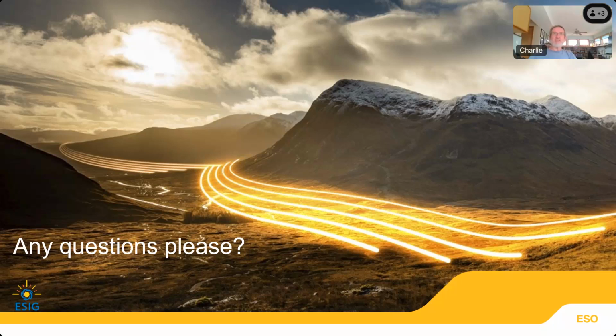Are there any regions within GB or other interconnected regions where inertia requirements are shared between regions? Is there a mechanism to coordinate this process? So GB is an island grid. It's a power system which is unique to GB. So whilst we're interconnected with HVDC links to Europe and to Ireland, we're an island grid. So there's no interactions really between inertia with different synchronous areas.